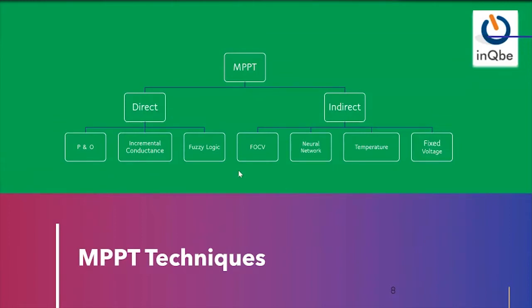Direct MPPT means the operational condition will vary directly, that is, we will vary the duty cycle of the converter. Methods include P and O, incremental conductance (INC), and fuzzy logic. Indirect methods include FOCV, the fractional open circuit voltage method, the neural network method, temperature based tracking, and the fixed voltage technique.